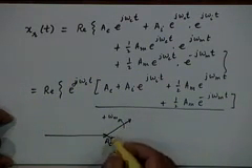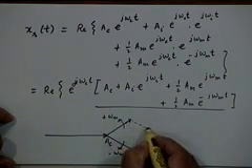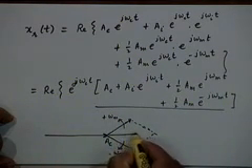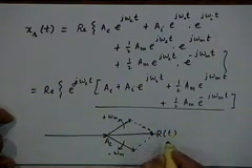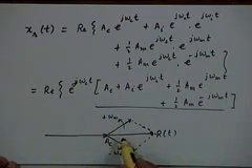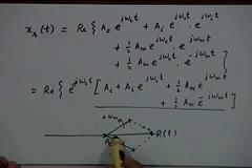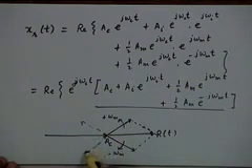So they are symmetrically placed with respect to the carrier phasor, and therefore the resultant wave by your parallelogram method, etc., would appear like this, right? R of t. The resultant will always be along this line. Is that clear? The resultant R(t) will fluctuate around A_c on both sides. For example, at this position, the resultant will lie here, right?